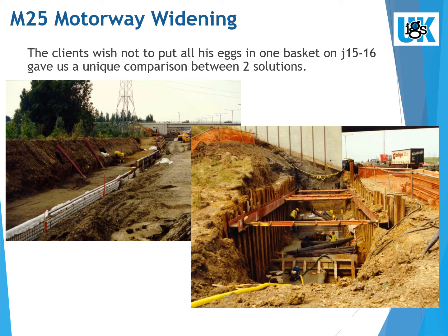The depth of foundations on the reinforced concrete cantilever necessitated sheet piling and dewatering to facilitate the casting of the cantilever sections, with imported fill being placed behind the walls when they were eventually backfilled. Due to the shallower foundation and speed of construction, the reinforced soil slopes were able to reuse the site-won materials.